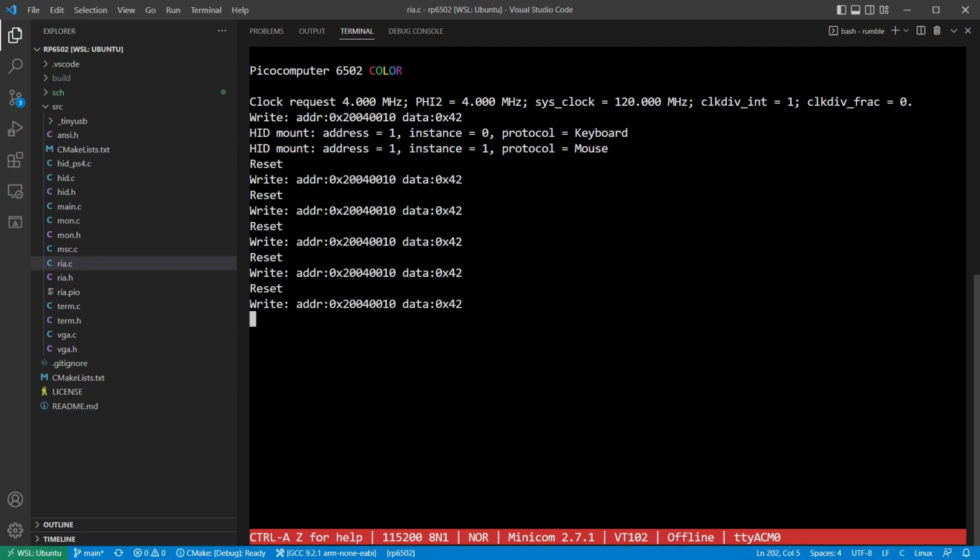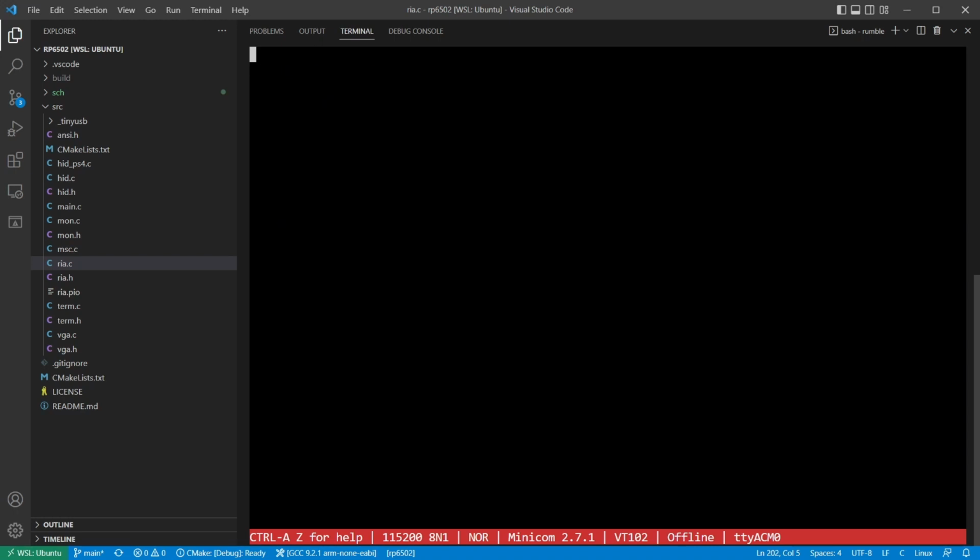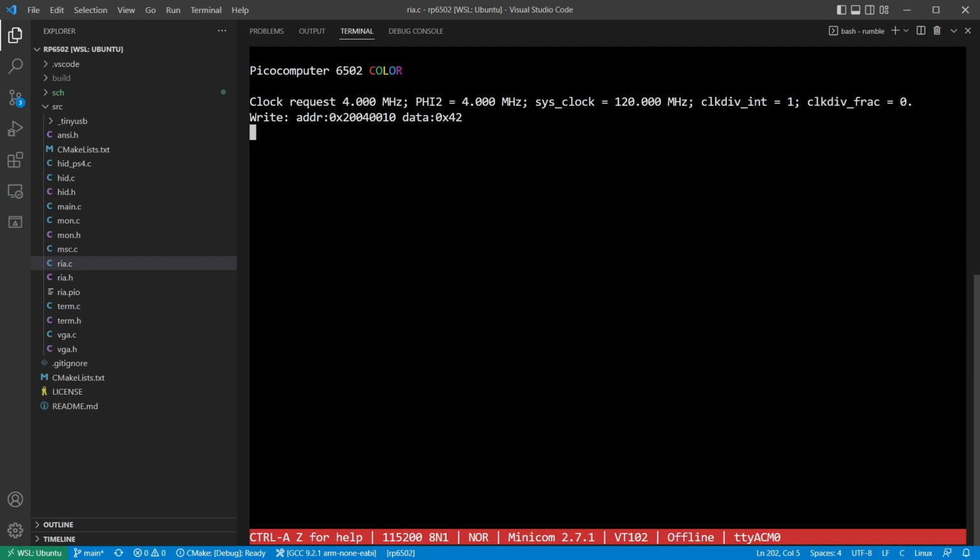I started at 4 MHz and didn't have any interesting problems, so I programmed up the ability to fully adjust the 6502 clock. The range ended up being from 1 kHz up to wherever it fails. I then built a test to automatically run through a list of frequencies. I hadn't yet tried for more than 8 MHz, and this would make overclocking easy.